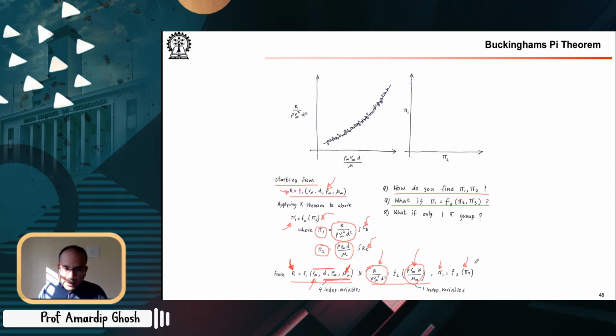Buckingham's Pi theorem will just give you the non-dimensional groups. In some cases, these non-dimensional groups will be physically relevant groups like the Reynolds number, Mach number, but there is no guarantee for that. It will be a non-dimensional group. Depending on the choice of repeating variables, etc., you might get things that are physically relevant like Reynolds number, Mach number, Prandtl number. Depends on the problem where you are applying Buckingham's Pi theorem to. But again, it can be shown that these non-dimensional parameters can be raised to powers, can be manipulated among each other to give you physically relevant non-dimensional parameters.